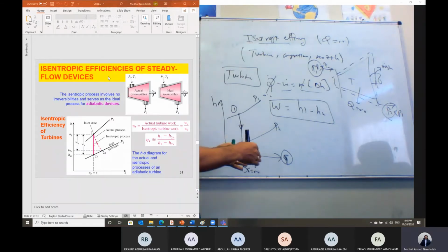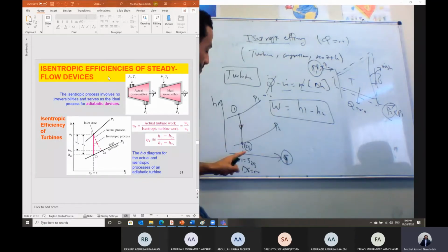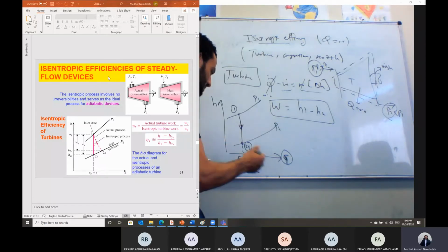If we have a system and the entropy is increasing, delta s is giving us indication about what in this system? About the losses within this system, exactly. So if we have an isentropic process, that means the process is reversible and adiabatic, so we don't have any kind of losses. So in this case, delta s is equal to zero, and we don't have losses within this system. But delta s gives indication about the losses.